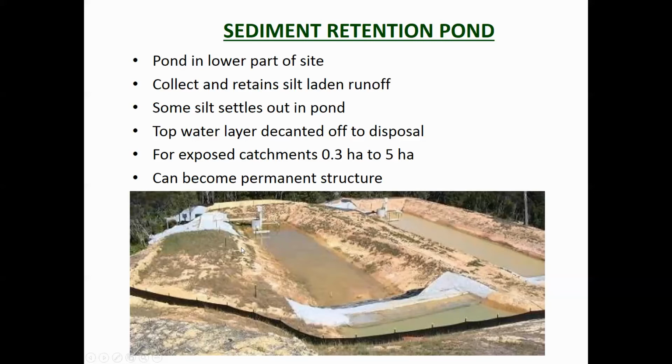What you do not want is the water level to get up high enough so that it goes over top of these. If it does that, then it's going to erode the bund out and the whole silt pond is going to fail. It's all going to flow out through that, causing more sediment in the stream than would have happened otherwise. So you've got levels of protection there. Ideally the water goes in, is taken off the top, it's decanted off the top by these. If they get beaten, it goes into the manhole off the top, so the top surface water goes into there. But if the whole thing gets beaten, then it flows over this diversion channel.